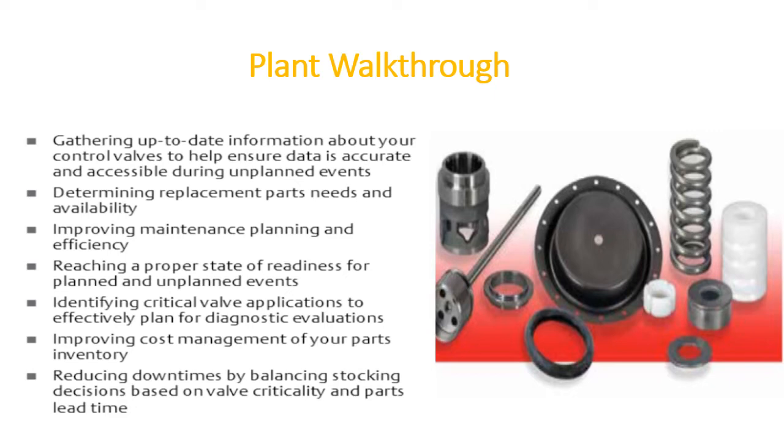So what spare philosophy should you follow? The best practice is to codify, or make a list of all the spares that are required, and make it available in the SAP system or CMMS system, or maintain one Excel, and buy the soft parts of all common valves.